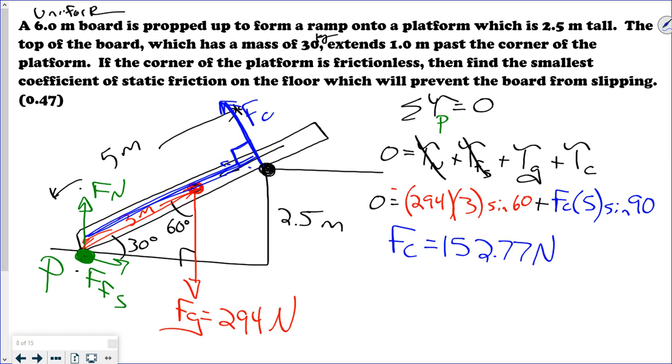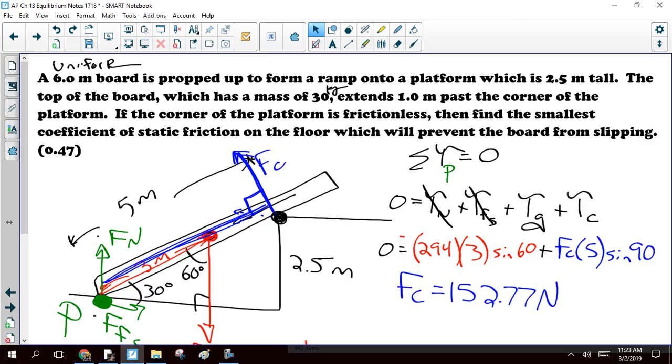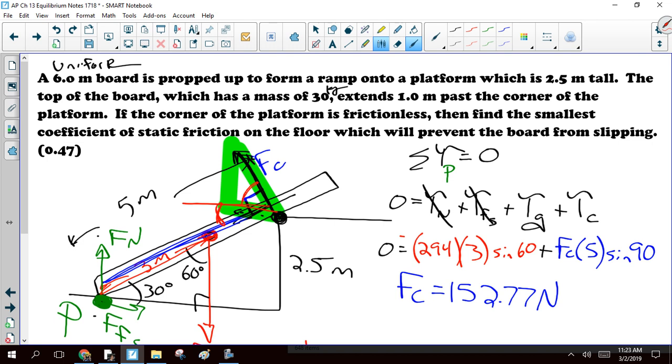So now I feel like we can go back to our forces. So that force has 2 components. So there's a triangle here, so there's an x component and a y component. And it turns out that if you draw in a horizontal line here, this is going to be 30 degrees, which means that this angle here is 60 degrees.